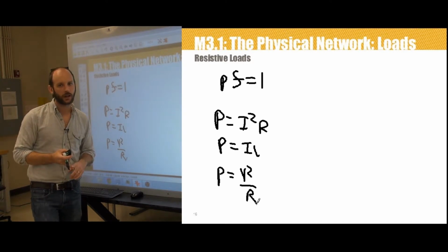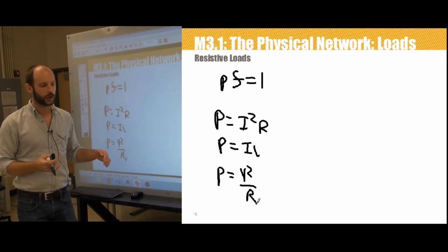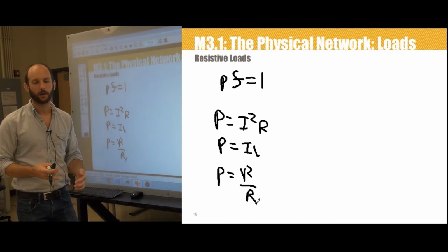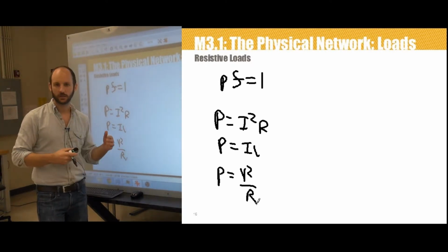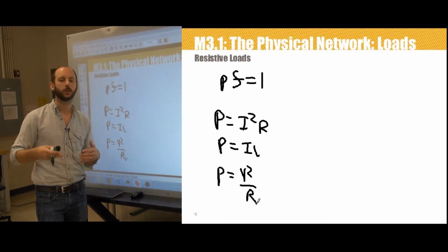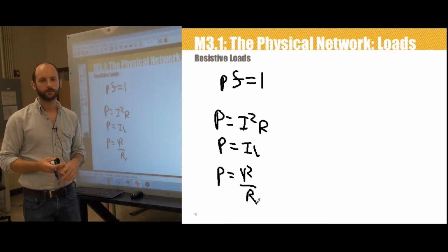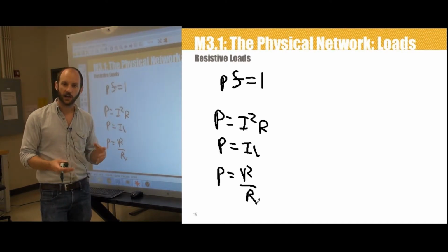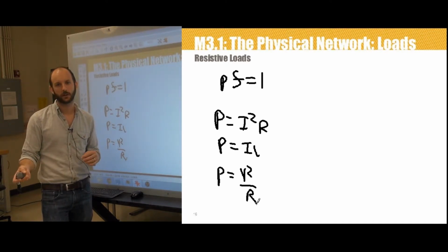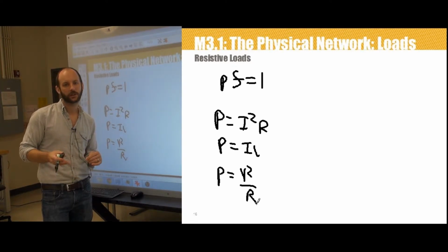They typically don't have that problem with low voltages. You can't put too little voltage on a light bulb, for example. It just won't light up. You won't damage it, though. They just simply consume less power, produce fewer lumen output. This behavior of purely resistive loads is kind of an important operational factor in the supply, because we don't actually supply 120 volts RMS.